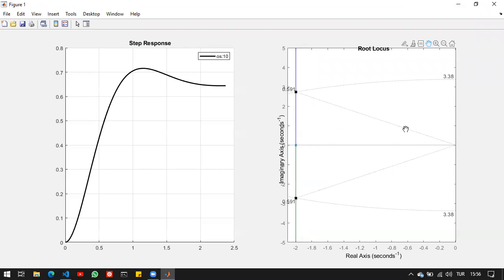The zeta values here can be chosen between 0 and 1, and each will correspond to a certain line here that will pass through this root locus. That exact point would be my solution for that specific zeta value. So I can decide on zeta, but I have no other choice than take the real value here.